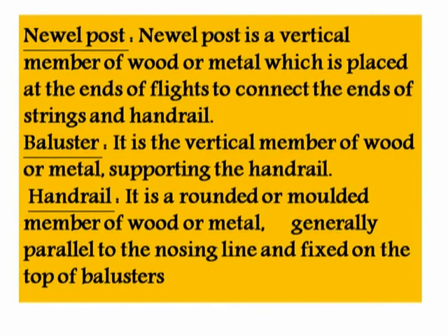Newel post. The newel post is a vertical member of wood or metal which is placed at the end of the flights to connect the ends of the strings and the handrail. So newel posts are provided at the end of the handrail. Then there is the baluster. It is the vertical member of wood or metal supporting the handrail.